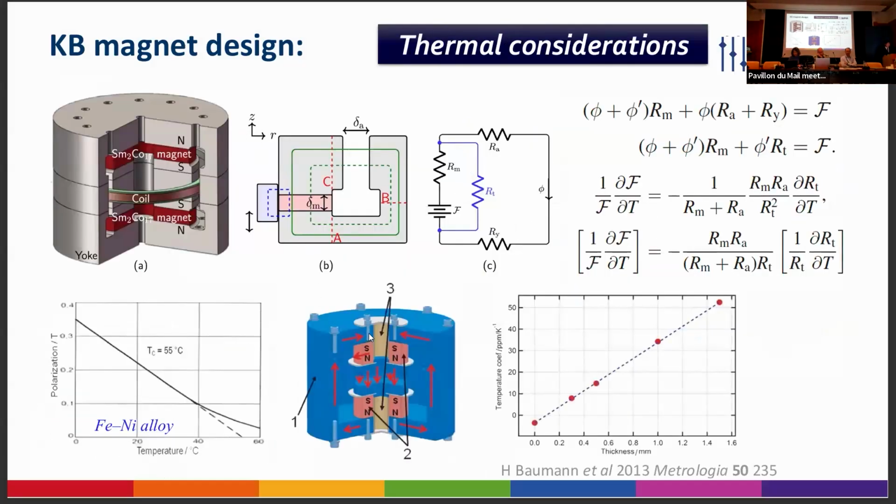For the temperature, you can do a temperature compensation like Metas did. The idea is you insert some shunt with a very high temperature coefficient. That means the permeability changes largely with the temperature. And they did a really nice compensation. But we also tried to do some compensation for the neodymium version, but it's very difficult. Maybe for small temperature coefficient, you can do this compensation. The idea is just simple, right?